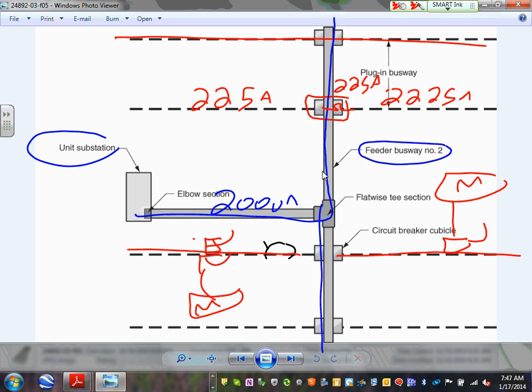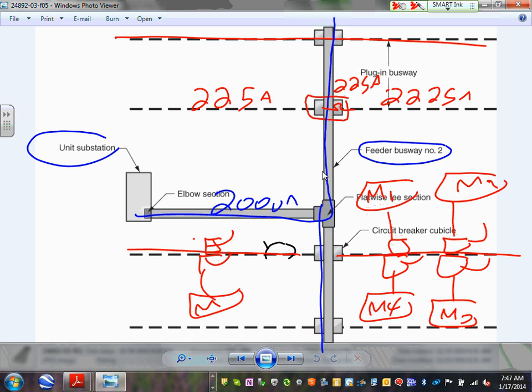This is exactly what you guys are going to be laying out in our project. You have a big feeder coming with big amps like 2000 amp. Then you tap that feeder with a smaller amp like 225, and where you put your plugs, all your plugs will be tapped with machine 1, machine 2. Here is machine 3, and this one here is machine 4, and so forth. You're looking at it right here.